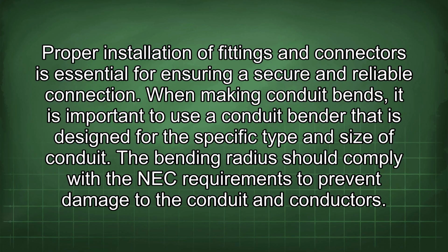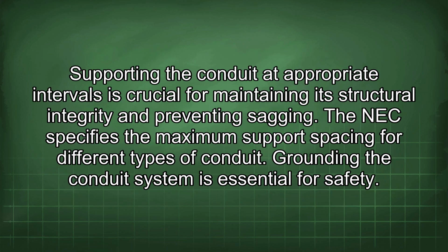When making conduit bends, it is important to use a conduit bender that is designed for the specific type and size of conduit. The bending radius should comply with the NEC requirements to prevent damage to the conduit and conductors. Supporting the conduit at appropriate intervals is crucial for maintaining its structural integrity and preventing sagging. The NEC specifies the maximum support spacing for different types of conduit.